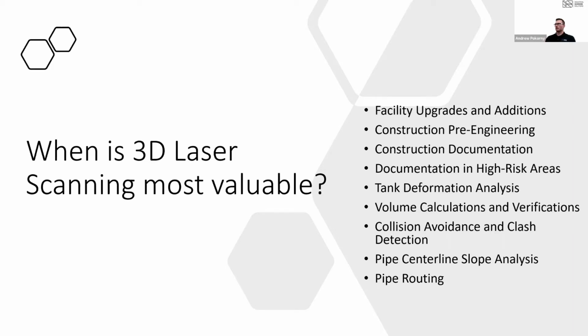Industrial facility upgrades and additions are a big one to really push 3D scanning, just because of the cost and the sheer volume of data that has to be captured, because with pipe routing or structural steel, so many things can be in the way. It's a valuable tool in the belt for an engineer to have that kind of information to design on, so you're not dealing with as many problems down the road, and everything actually fits correctly. You don't have to move things around or do custom fits in the field as often, and there's a lot of potential value with that.